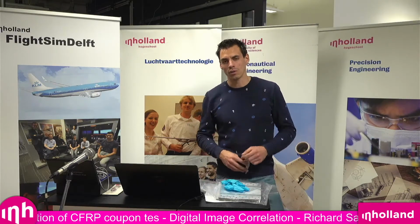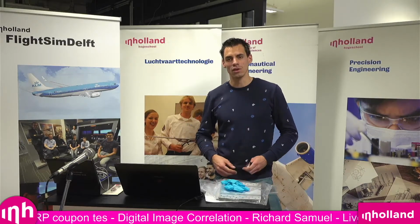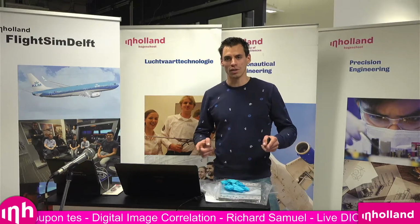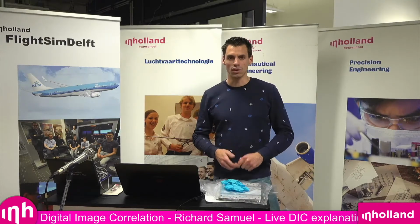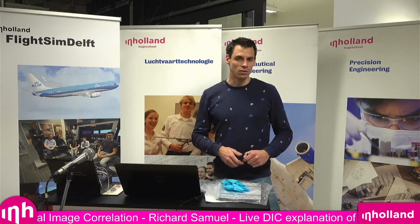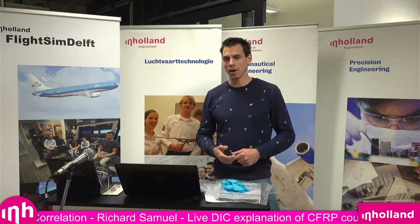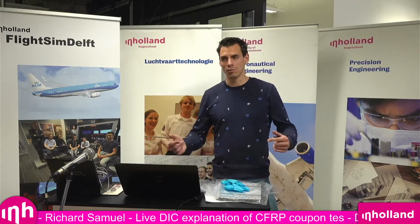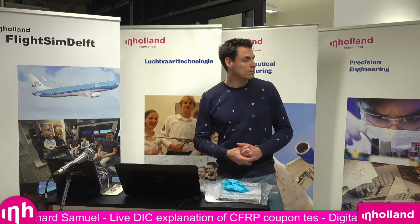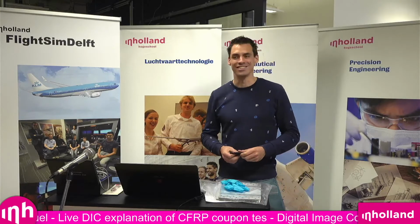However, a requirement from the ISO or ASTM standard for compressive testing is that you visualize the strain on both sides of your sample to make sure that there's no bending and that it's purely compressive. So typically you have to apply a strain gauge on both sides. To completely comply with the test, you need to have a camera on both sides of the sample. And indeed, a good excuse for a beast PC.